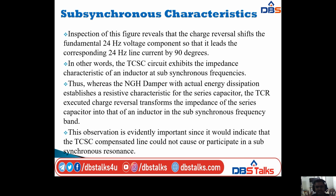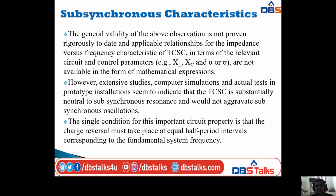So this observation is evidently important since it would indicate that the TCSC compensated line could not cause or participate in a subsynchronous resonance. Next, the general validity of the above observation is not proven rigorously to date, and applicable relationships for the impedance versus frequency characteristics of the TCSC, in terms of the relevant circuit and control parameters, those are XL, that is the reactance across the inductor, and XC, that is the reactance across the capacitor, and alpha or sigma, are not available in the form of mathematical expressions.